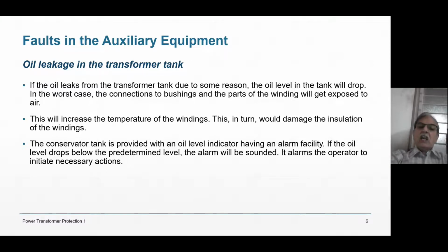And at the top of the Buchholz relay, once again, the trapped air is there. If the oil is gasified because of minor fault, then that small gas will go into the Buchholz relay. So oil level in the Buchholz relay will come down and the Buchholz relay will operate, sounding an alarm.